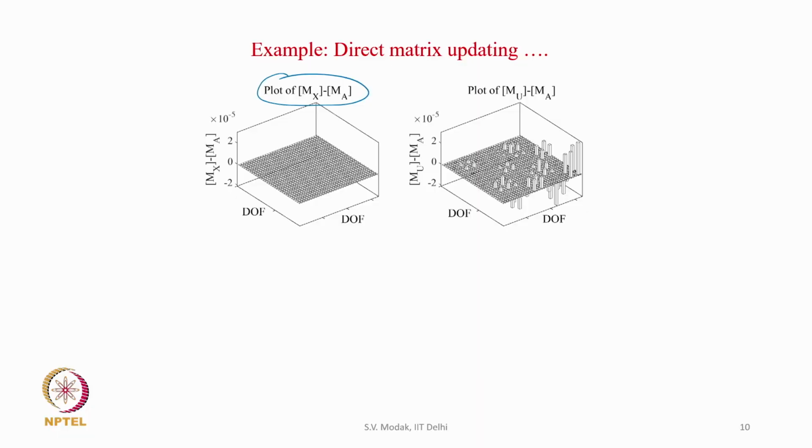And we see that actually there was no error in this matrix, because the discrepancies between the FE model and the experimental model were related to the modulus of elasticity, which does not affect the mass matrix, and the torsion stiffness Kt, which again does not affect the mass matrix. That is why there was actually no error in the mass matrix.